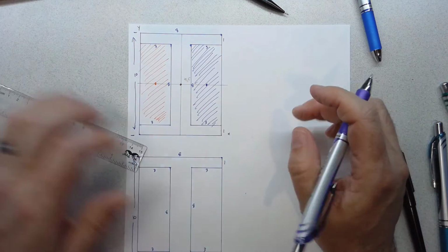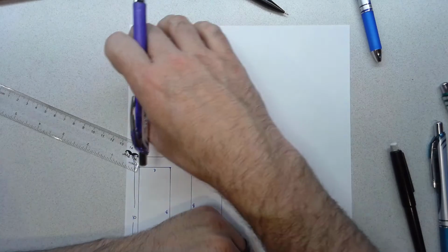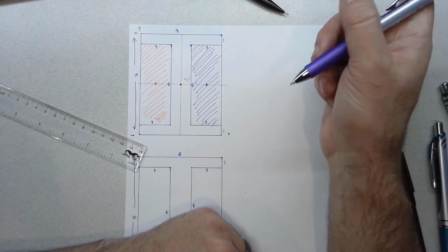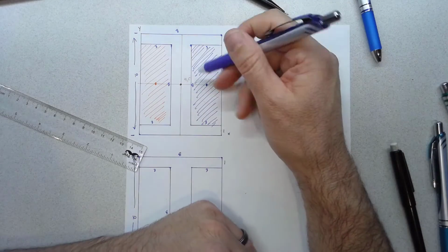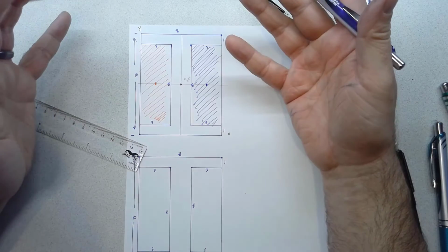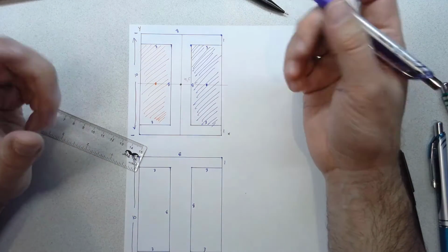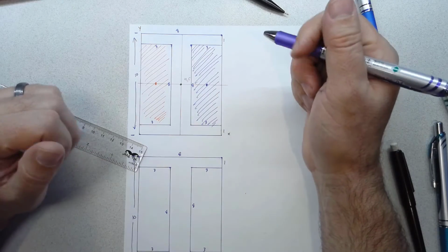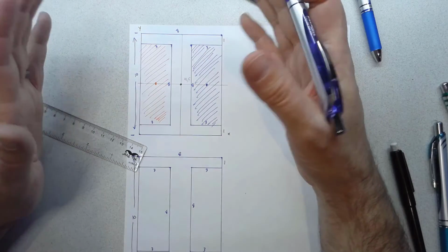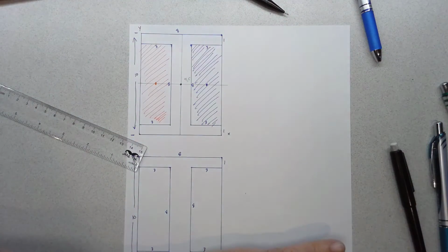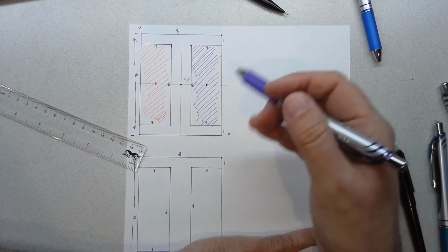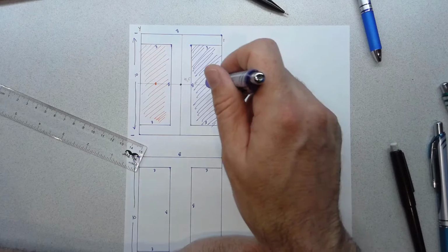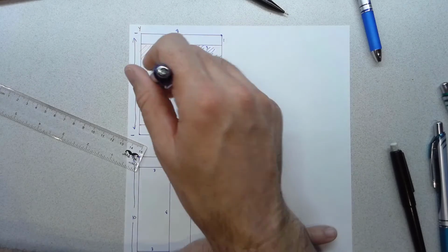So there are the centroids of the whole rectangle. The left part we're going to subtract, and the right part we're going to subtract. And why I'm marking those out right now is, when we're looking at I, or the moment of inertia, we can add and subtract the composite moment of inertia of each piece to come up with a total. So in this case, we're going to take the moment of inertia of the whole rectangle and then subtract each of these sides here.